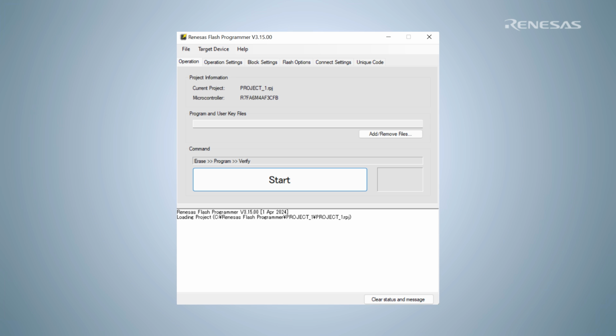In this video, we are going to take a look at a handy feature in the Renesas Flash Programmer, uploading our program onto the array board in boot mode. You may be already familiar with using the Flash Programmer application through the JLink onboard debugger. But let's say you don't have the JLink debugger available on a custom-made system. How do you upload the program then?